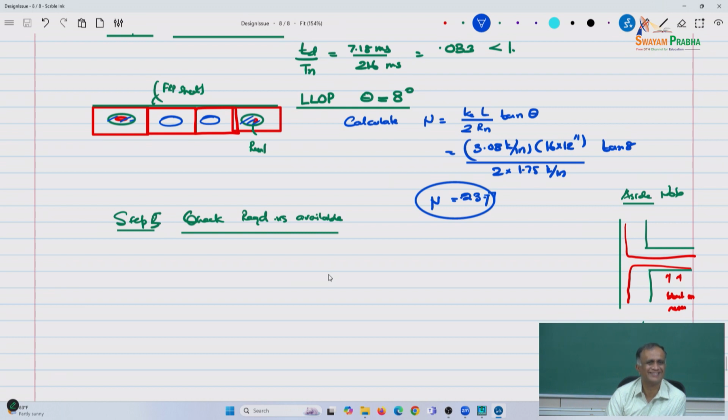What are you thinking? Mild steel plate? Well, you're changing properties. A, it's expensive. B, it's heavy. Third, how are you going to connect these plates to the brick wall? So that's not a solution I might go with. It's prohibitive in some cases. It definitely helps in strength, but a masonry wall is not for that purpose. But if you're going to protect something valuable, whatever the asset inside, that's a consideration. If you put a small thin aluminum plate or mild steel plate, it becomes a composite structure. There are designs of composite sections. We can do that, and then you get into composite designs for calculation of your moment capacities.